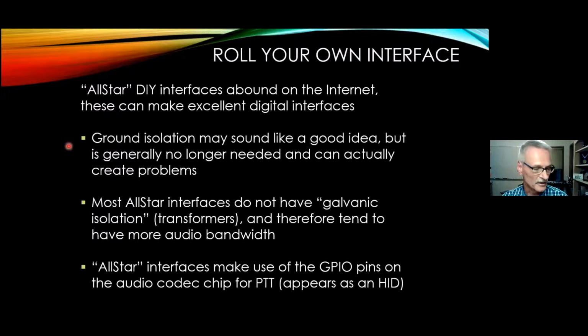When they called me up about it, I suggested they take the transformers out altogether, and they said they're experimenting with that, but they're afraid to do that. So we'll see. But you're not going to get high-speed performance with little tiny transformers inside your devices. They're just too limiting in the audio bandwidth.